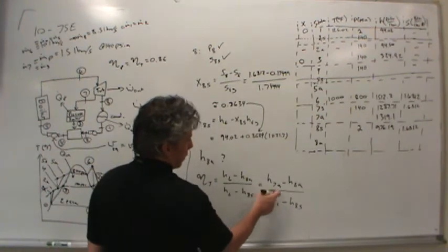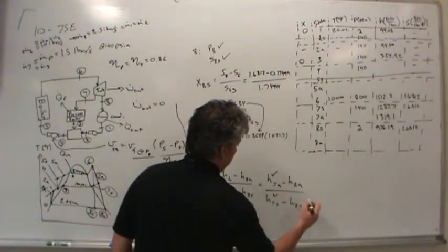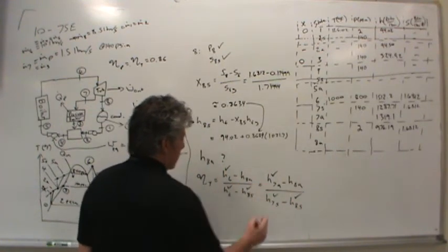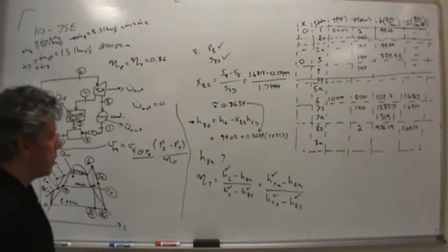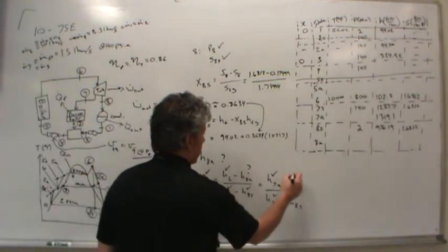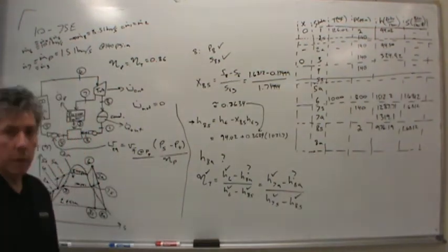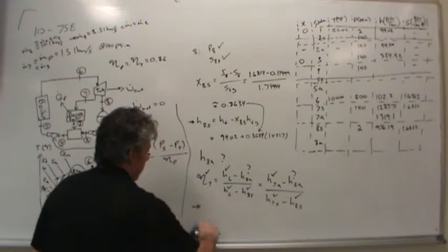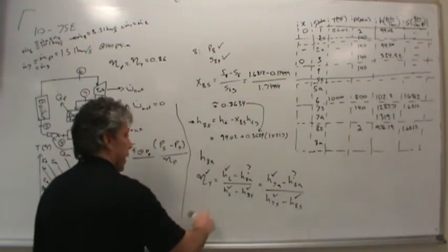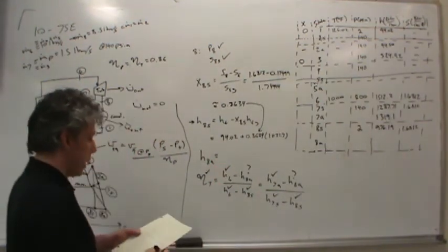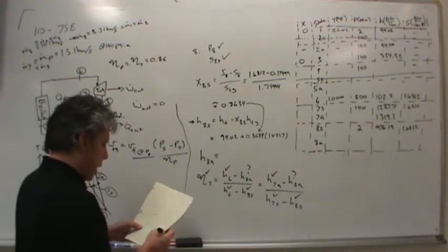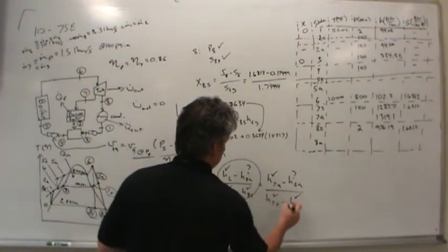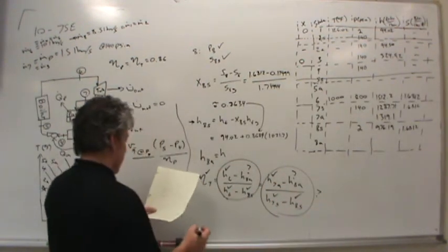Notice that you've already got these, you've got 7A, 7S, you've got H8S. Similarly, we have H6 and H8S. And so the only unknown, since the isentropic efficiency is given, is state H8A. So to calculate H8 actual, the enthalpy in state 8 actual, I'm going to use this first form. You can try this. Let's see if it works. It should.